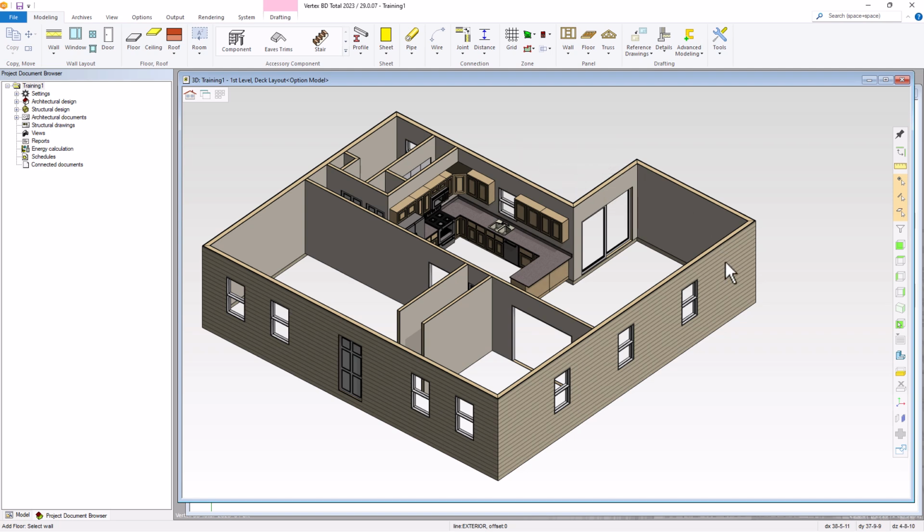But if you go and add another series of walls, let's say a bump out here, and you draw 3 walls, then it's going to use those 3 walls to place the floor system. It really depends on when you drew your exterior walls and if they're all linked. So I'm going to right click and show you how that works. In this case, it will work fine because all we have is one series of exterior walls. So I'll click. It found all our exterior walls, and the floor was added based on the wall location.